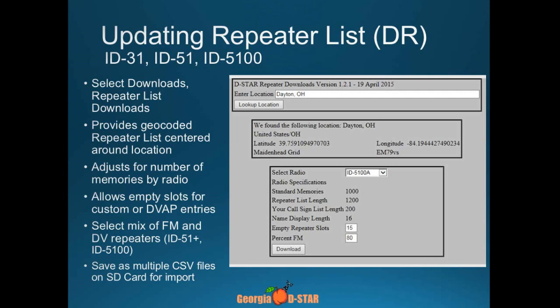That's a very good question. Before you do anything with that SD card, put it in your radio, go menu, and all the way to the end is SD card, format, and let it format in the radio. The reason it does that is that it sets up a certain 4 or 5 folders. One of those is called settings. If you save the settings of the radio, that saves everything: all your menu settings plus all the regular memories.